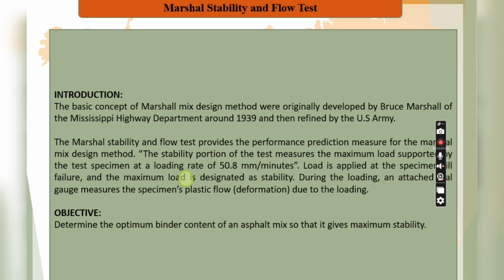As I said, the Marshall stability test is applied to check the resistance to plastic deformation of bituminous material and its maximum strength. So what is the objective? The objective is to determine the optimum binder content of an asphaltic material that will give the maximum stability.